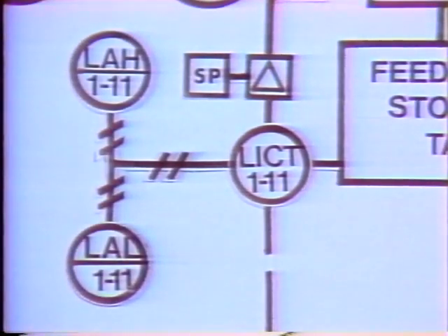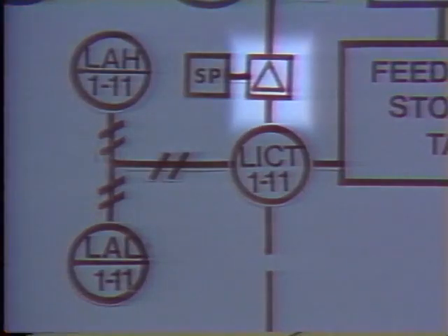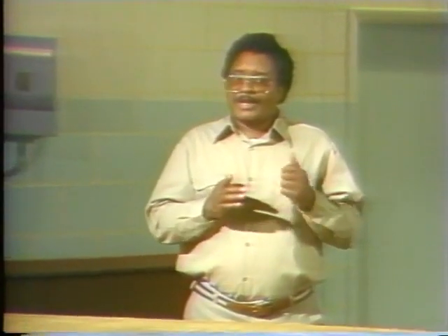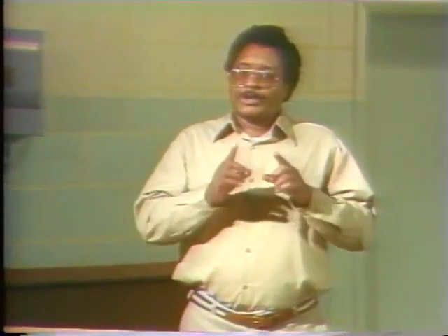The transmitter is used to send an output signal to the third additional component needed to make this an automatic system, the comparator. A comparator is a device that looks at 2 different input signals, decides which one is larger and by how much. Then it sends out a signal proportional to the difference between the 2 signals.